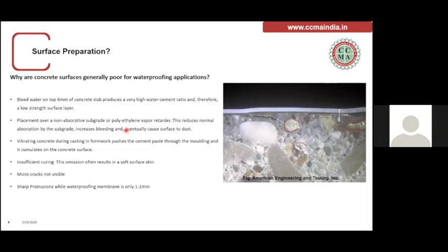I would like to explain further why surface preparation is required. Generally with concrete, while you are doing the vibration, there is a high tendency that the bleeding water comes to the top 6 mm of the concrete. So if we are doing any bonded system over it, what can happen is that the top layer of the substrate is weak. That can potentially debond, and the waterproofing can potentially crack because of this.